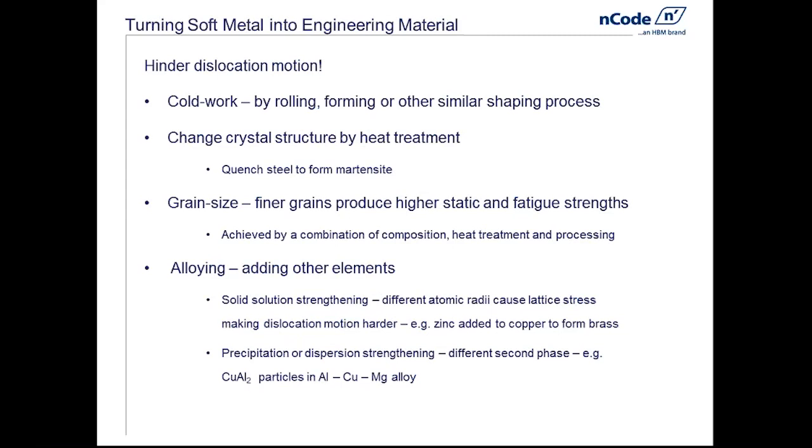You cold work it, you roll it or thump it or do something to it and reduce the thickness, and you increase the population of the dislocations. And if you think in terms of that sort of network of little black lines, you can turn that by increasing that into an almost lace-like structure with the metal. And because they are interlocking like that, they make it very much harder for you to pass another dislocation through it.